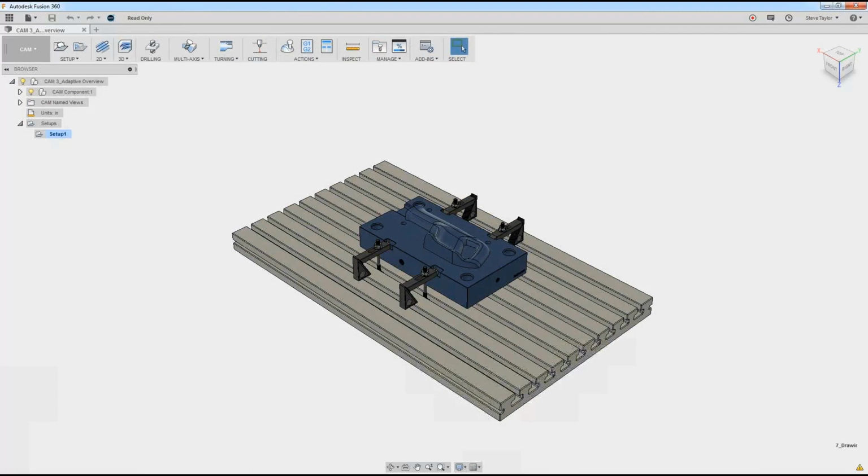So we have the same setup orientation really as we did before. By using this standard model, we ensure that we didn't make any mistakes that are going to carry through to this. Now we don't always have to start out with 2D toolpaths, but for this one, we will do an initial 2D toolpath using a 2D face.